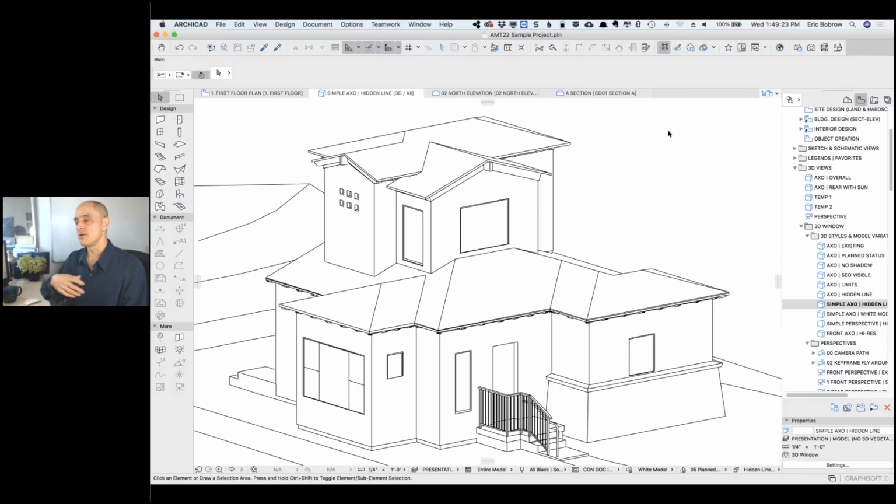So if you see funky lines on your elevations, you will see it in Analytic hidden line. You won't see it in renderings necessarily or in the other 3D viewing style there. Now, the trade-off is this is beautiful, or it's clean, and it's exactly what you would see in an elevation. When you're doing it in hidden line, we can do this with more detail.